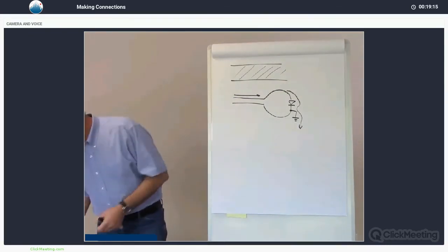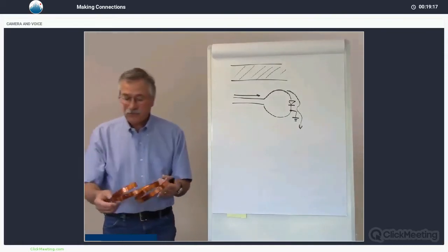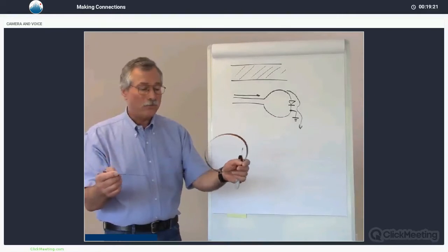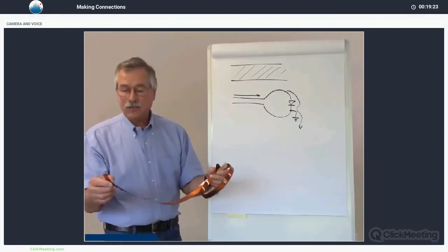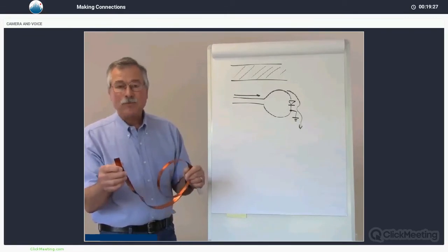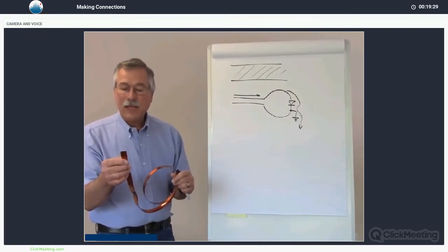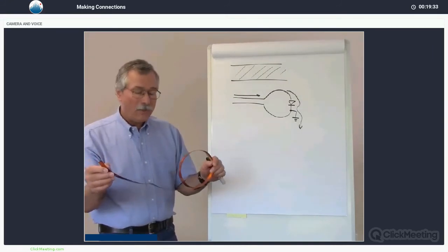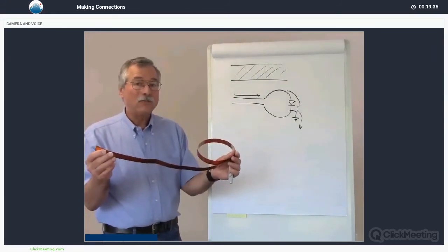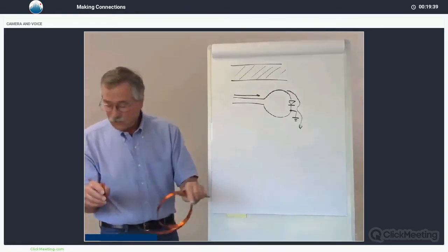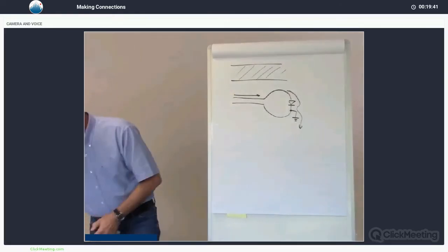We have a couple of other examples here of strip line. This is a small, much more flexible strip line that is used with modular or single board type pulsars. It's basically two strips of copper separated by some kind of Kapton or similar insulator, very thin, very flexible. Again, use the minimum amount necessary to do the job. It still has inductance, although not so much.